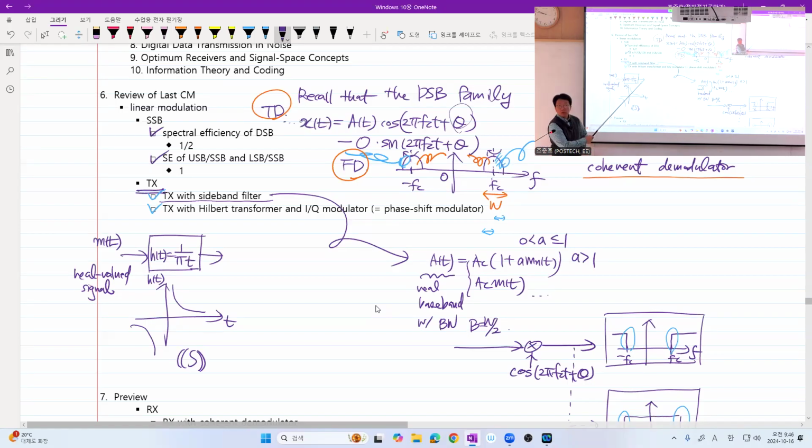What is the output? Is it real valued or complex valued? As you know, the output is a convolution integral with the integrand being the product of the input and the time-shifted, delayed version of the impulse response. Both of the signals are real valued. So the output cannot be complex valued with a non-zero imaginary part. So automatically we have a real valued output. Got it?